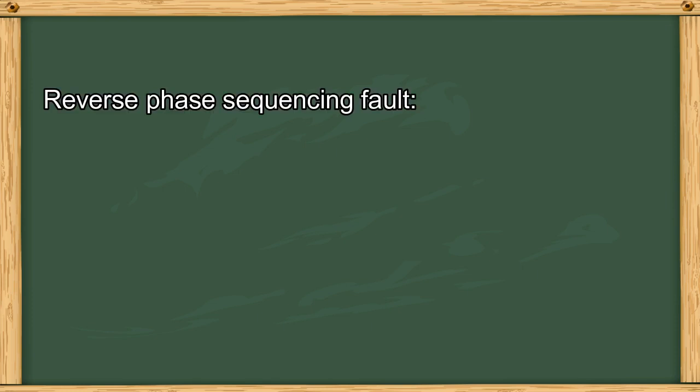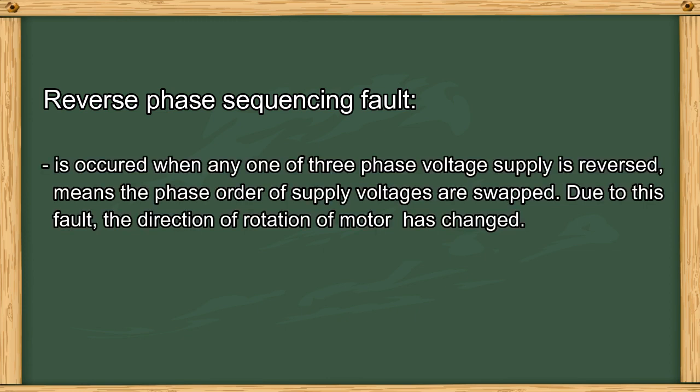Okay, the second one is reverse phase sequencing fault. The reverse phase sequencing fault occurs when any one of the three phase voltage supplies is reversed, meaning the phase order of supply voltage is swapped. Due to this fault, the direction of rotation of the motor has changed.